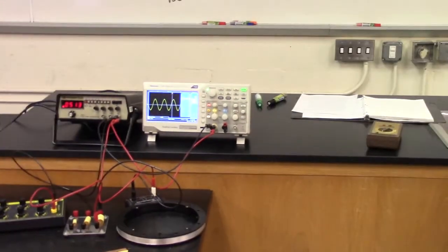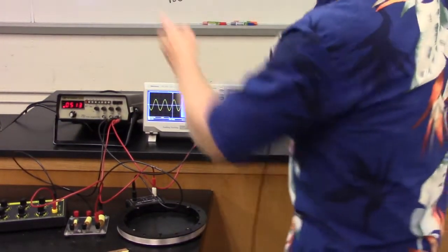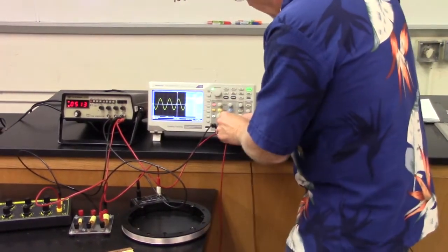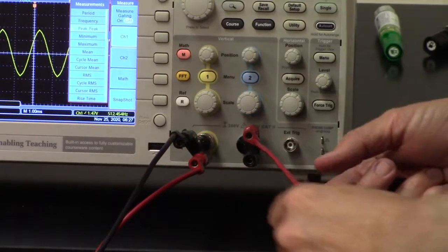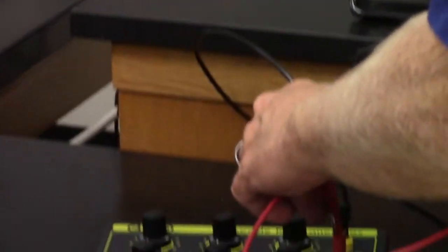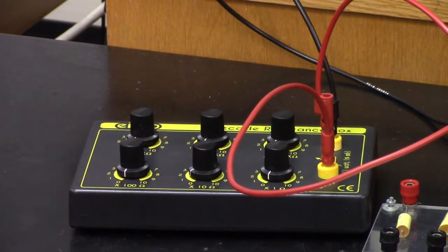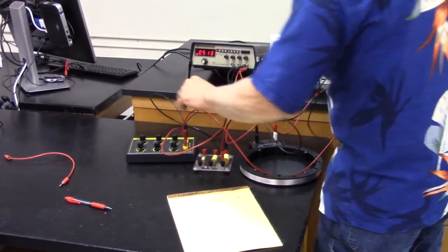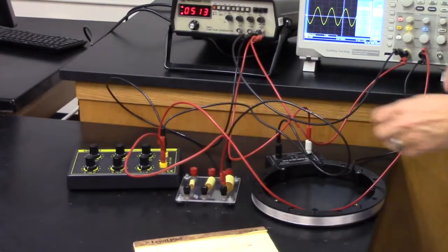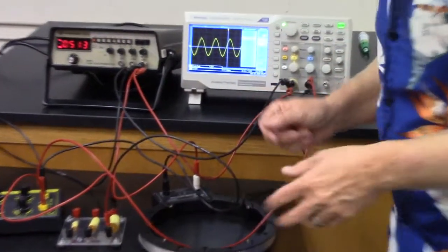So here's channel 2, and I think that wire over there is kind of short. Let me get a little longer one here. But as I was trying to show there on the diagram, channel 2 is going to be looking at the voltage across the resistor, which we will use then to convert into a current. And so I will put channel 2 there. And so now I got a mess of wires, but that's why I wanted to set it up in front of you so you can kind of see what I did.